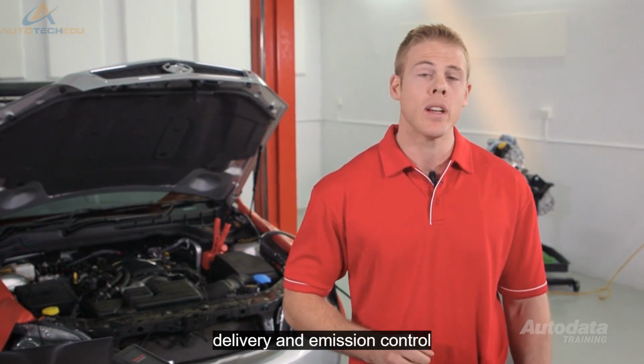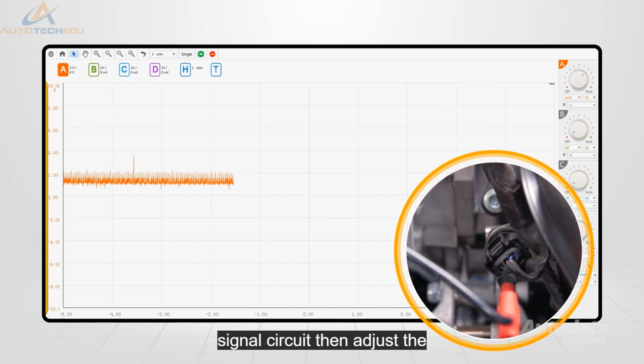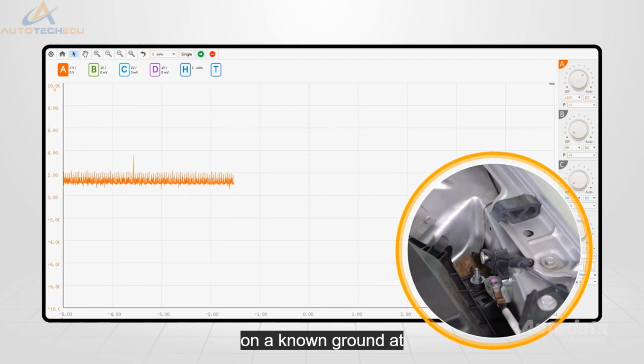The fuel rail pressure sensor is another component that provides pressure information to the ECM for finer adjustments to fuel delivery and emission control. To connect, back probe the sample lead at the signal circuit, then adjust the Y-axis to 10 volts and the X to 1 second. Place the black lead on a known ground.